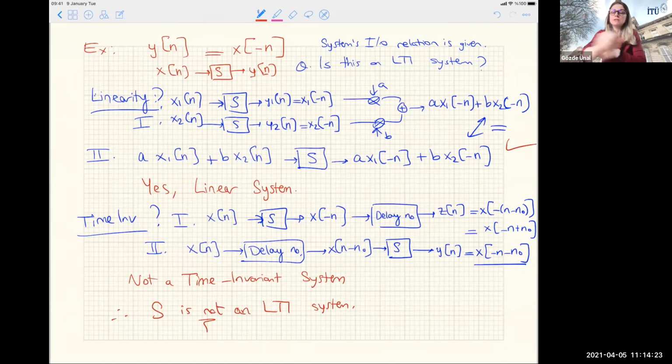Superpose those outputs, or sum the inputs, superpose the inputs first. Scale also, of course. Scale and sum the inputs, send it to the system, and the system produces the same result as before. That's linearity. Time invariance is a similar idea: whether you execute the signal through the system first, then delay the output, or first delay the input, then execute the system, gives the same thing.